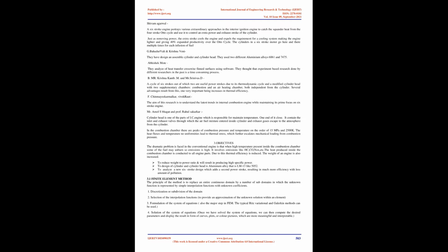Less fuel is needed and it also increases power. It reduces the weight and complexity of the engine's head by as much as 50%. Torque is increased by 35% and it also increases efficiency. The 4-stroke block, pistons, and crankshaft remain the same. This combination of 2-stroke and 4-stroke technology is named the 6-stroke engine. 2 + 4 = 6. Functionally, the second piston replaces the valve mechanism of a conventional engine.